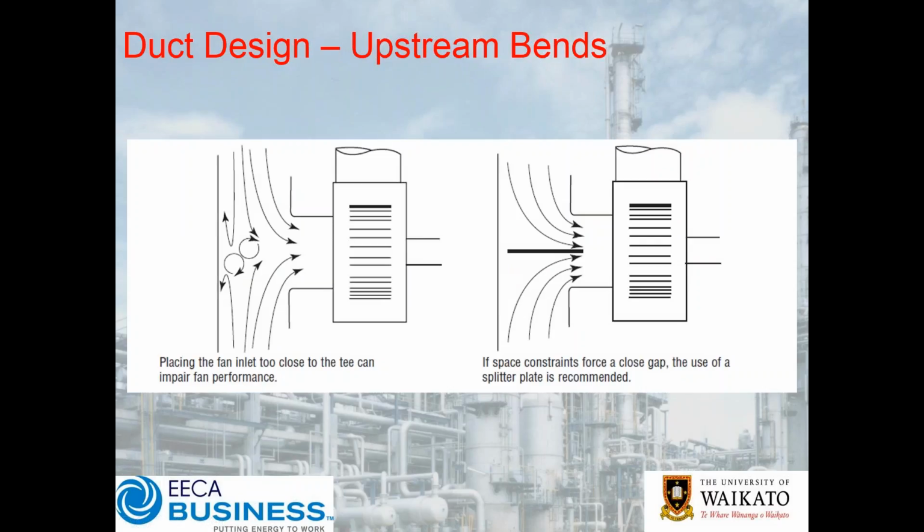Another really common problem that we see with duct design and troubleshooting with systems is where you have multiple ducts coming together. So often you'll see this where you have a single large air handling unit. It might be a big extraction fan or a big exhaust fan off a process. You might have multiple ducts feeding into a common system, and what you have to pay close attention to is when they come together, especially right in front of a fan like this, these flows are turbulent, and at any given time if you were to plot the velocity in this top one, it's not actually a straight line.